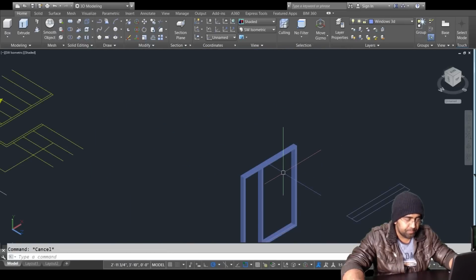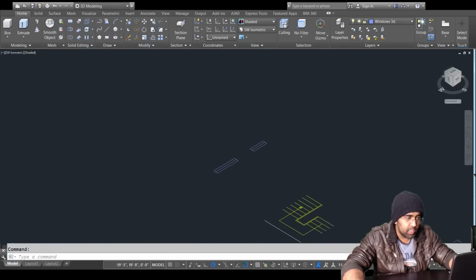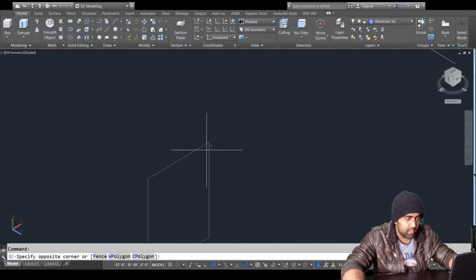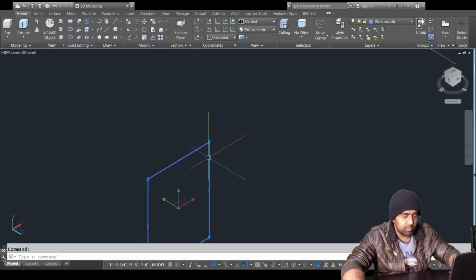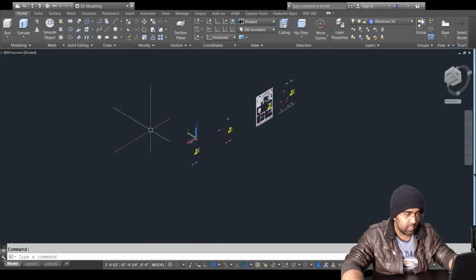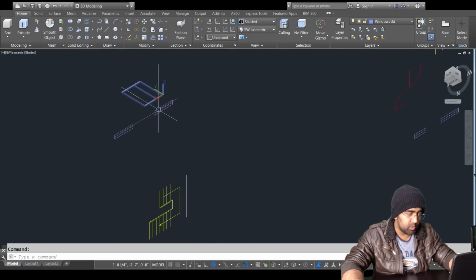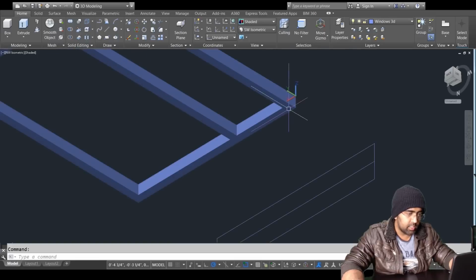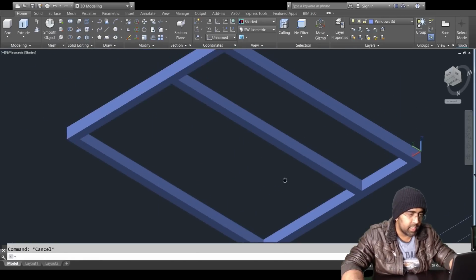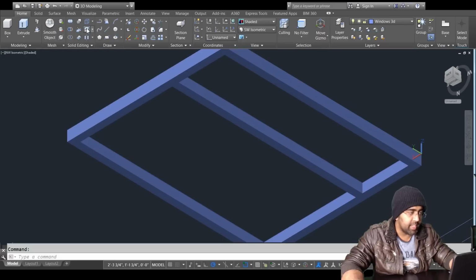Now what we can do here, I've made a copy here somewhere here. Okay, so let me just get rid of it. We don't need that anymore. So I'm going to click on this view cube. I'm going to change the viewport to backwards. Okay, so this is a backward view, and now I'm going to copy something here. So to copy face, there's a command here, extract edges. Okay, and then copy edges.